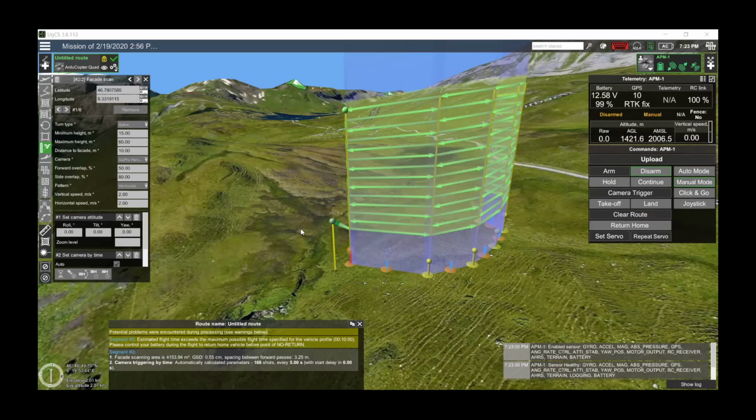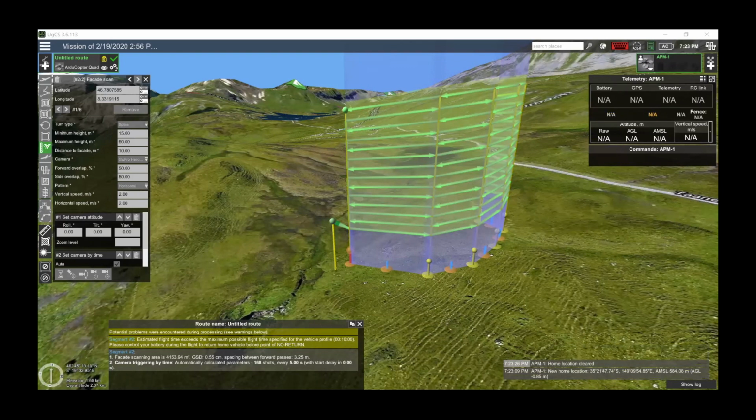Still some problems with the simulator. You can see on the screen there's a little green path. Right now on the screen you can see which part of the route the drone has already completed, and after route resume, the drone will continue from that exact location, and it will not be necessary to specify a waypoint. This option to specify a waypoint still remains, because sometimes with some sensors you would want to resume a route from an earlier stage than you finished before.